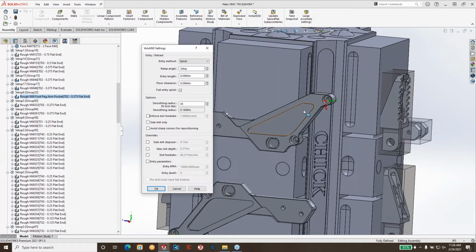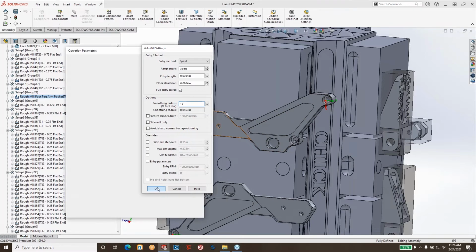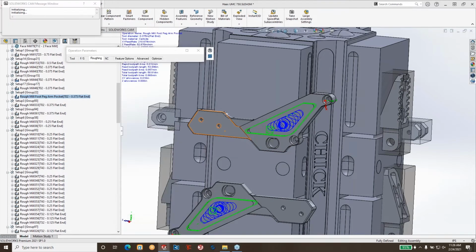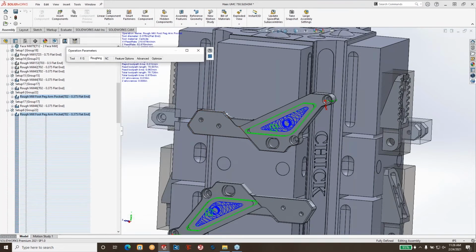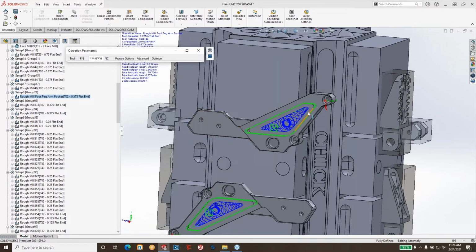And you could see the toolpath didn't go all the way up in there when I was on it, right? There's an adjustment here. I could say, hey, make this, I don't know, we'll make it 15 or whatever, right? And that allows the tool to start squeezing down tighter into those tight spots, right? And now the tool is really working where it needs to up inside that radius that we changed earlier.